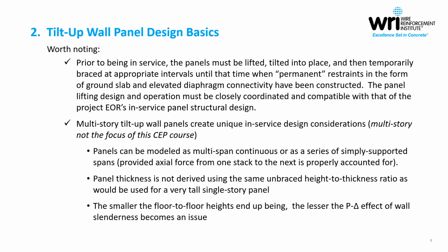With that in mind, the P-delta effect for multi-story tilt-up isn't quite as pronounced as in tall single-story warehouse type or distribution center type applications, simply because the floor-to-floor heights are significantly smaller. So always worth a mention, tilt-up is a very useful solution for structural construction. Multi-story is certainly not off the table, but our focus here is going to be on single-story construction, primarily distribution center, warehouse type, industrial type applications.